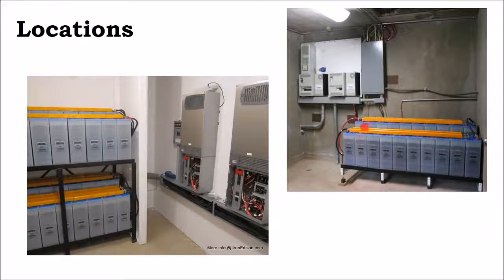The batteries stick out more than 6 inches from the service panel. Now, we do have 6.5 feet of just electrical space, and we do have the width of the equipment, or 30 inches of access on this side, aside from that depth violation. But then we also have some other items of concern.